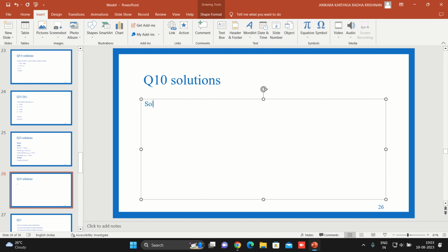So, how do we find the solid fraction inside the bed? It is equal to volume of solids divided by volume of bed. From the previous two questions, we found it as 700 ml and 1570 ml. So the volume of solids inside the bed was 700 ml and the volume of the total packed bed was 1570 ml. So dividing both would give us the answer as 0.4459. So what would the void fraction or porosity value be?